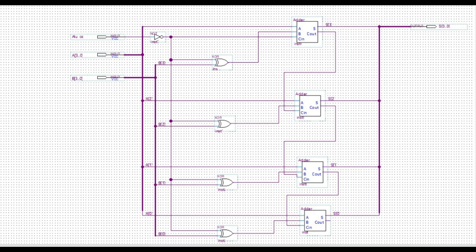Then we create a bus line connecting to input A of each full adder and name each line A0 to A3. For our 4-bit D inputs, we connect each of them with a carry in input, connect exclusive or to B, then the first Cout to the second adder, and so on respectively, but you can ignore the final carry out bit signal. The same goes for the sum from S0 to S3 using the bus line. Lastly, export this block to a block symbol.